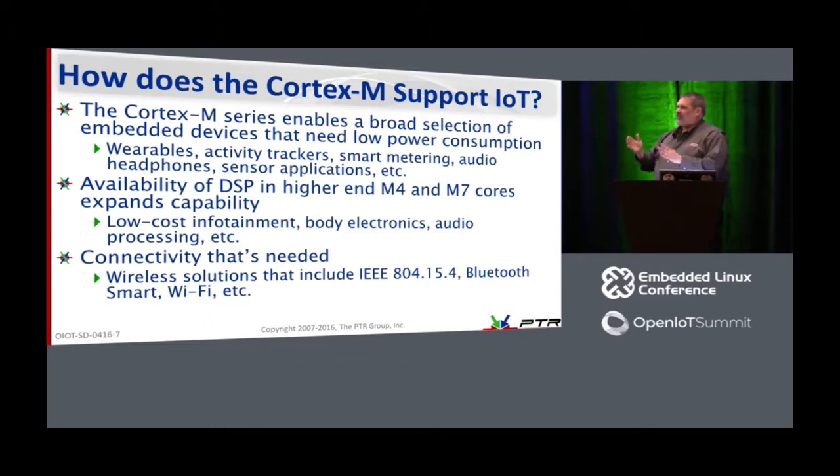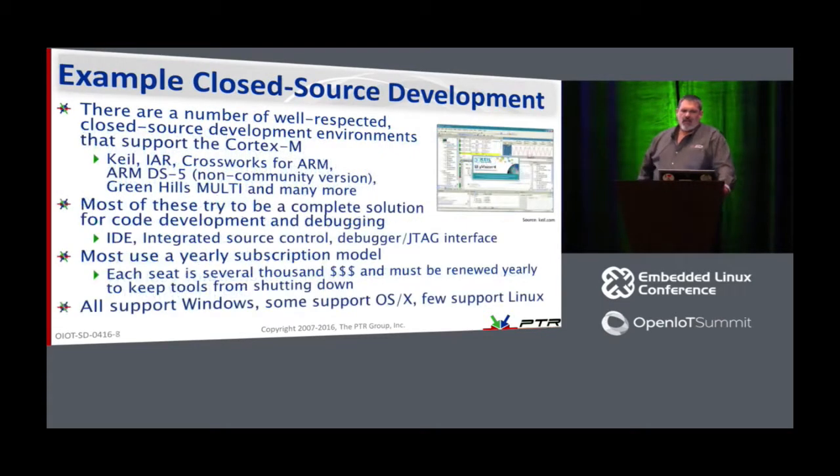But we want to make sure that we do that in such a way that we don't expose ourselves to a large amount of attack surface. Now, the radios out there have Bluetooth, Zigbee, 802.15.4, 6LoWPAN. They have all these different protocols already built into them. You just buy the module, you plug it into the UART, and wham, you've got connectivity. It's not that complicated, fortunately.